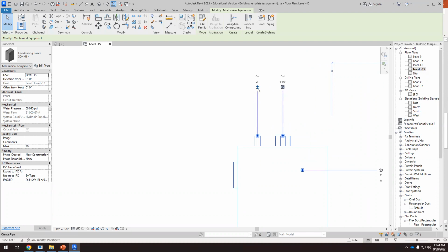When we have water, we have this closed loop with a pump. You see, well, the symbol here is very small, but it's a closed loop with a pump. Okay, so this symbol means that it's water and it's a closed circuit. Well, it can be water or any other, it can be the refrigerant fluid as well, but it's a closed circuit. So this is the outlet.